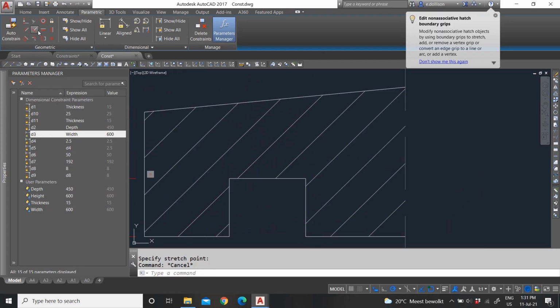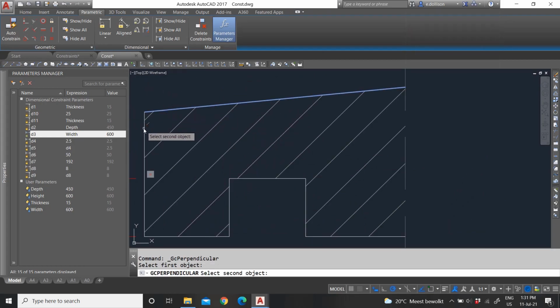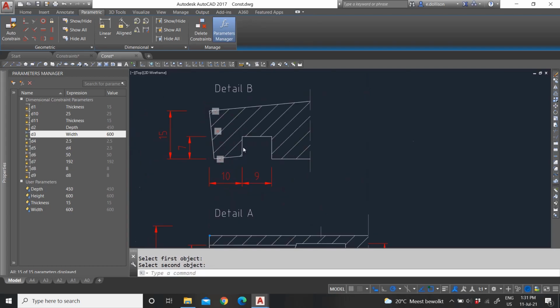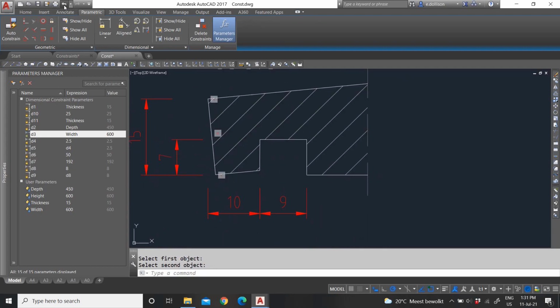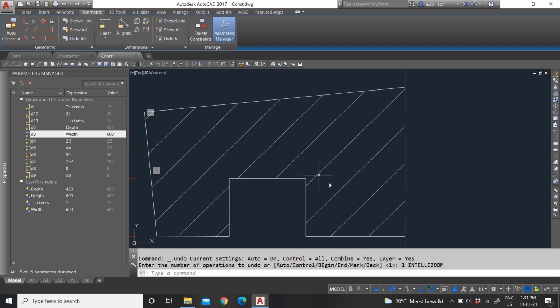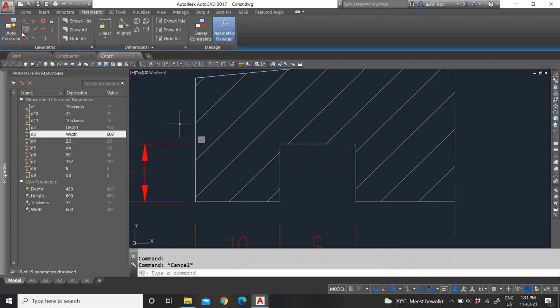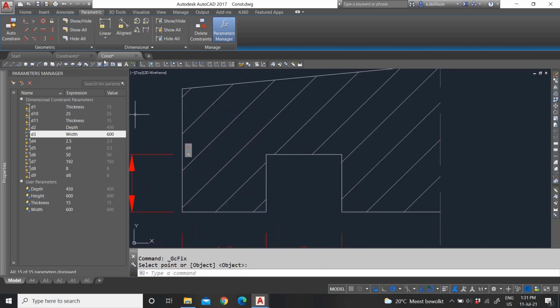And here we have our perpendicular problem. So this has to just remain 90 degrees, sorry, and also this right here should also be 90 degrees to this one. There's always a problem. Make sure, guys, that first of all, something is constrained, so let us just lock, first of all, this corner or the line and then make it perpendicular.